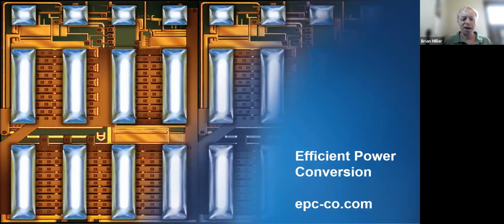It actually works okay because in many designs you can have a bottom plane which can be ground and a switch node internal. But even if it's not an internal, there's a lot of designs with a switch node on the top, and that works pretty well for the EMI. The inductor helps to limit the current going into it.